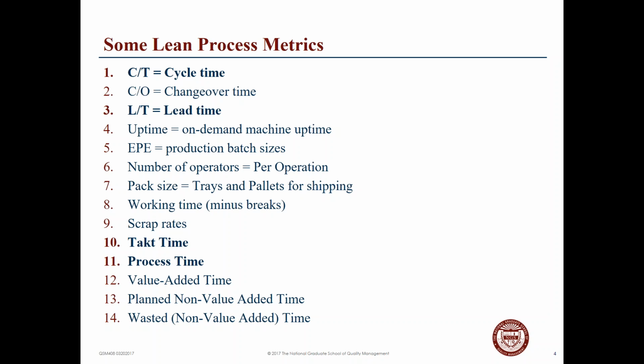Lead time, meaning how long does it take you to fill the order from the time you receive it until the customer receives it. Uptime is one that is often measured in manufacturing. It's an indicator where we are looking to see how much the equipment is up and producing product. A lot of times, due to maintenance issues, supply issues, personnel, we can end up with lines sitting idle. So uptime is a measurement that we use often to ensure that the machinery is producing product at the rates they're supposed to.